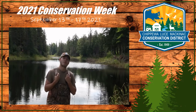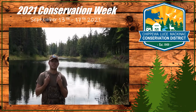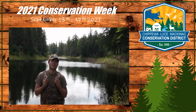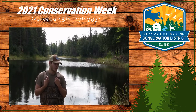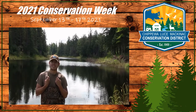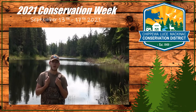The second parameter I'm going to look at is dissolved oxygen. Dissolved oxygen is a measure of the oxygen dissolved in the water. Oxygen levels can vary from 0, which is no oxygen, to levels as high as 18 milligrams per liter, which is high. Typically, in most systems that support a healthy fish population and other aquatic organisms, we're going to see dissolved oxygen around 6 and above. That's typically a good level for fish to grow, reproduce, and spawn, and along with other organisms to survive in